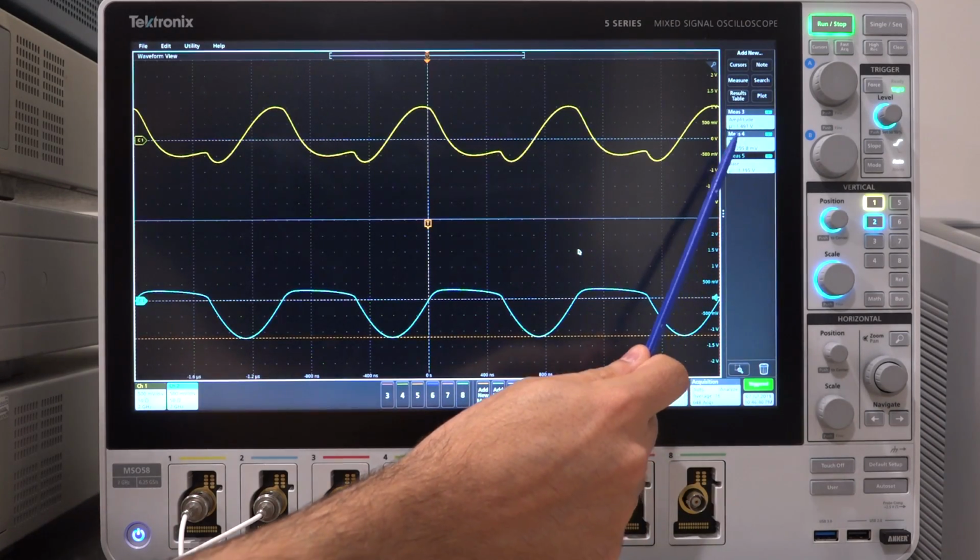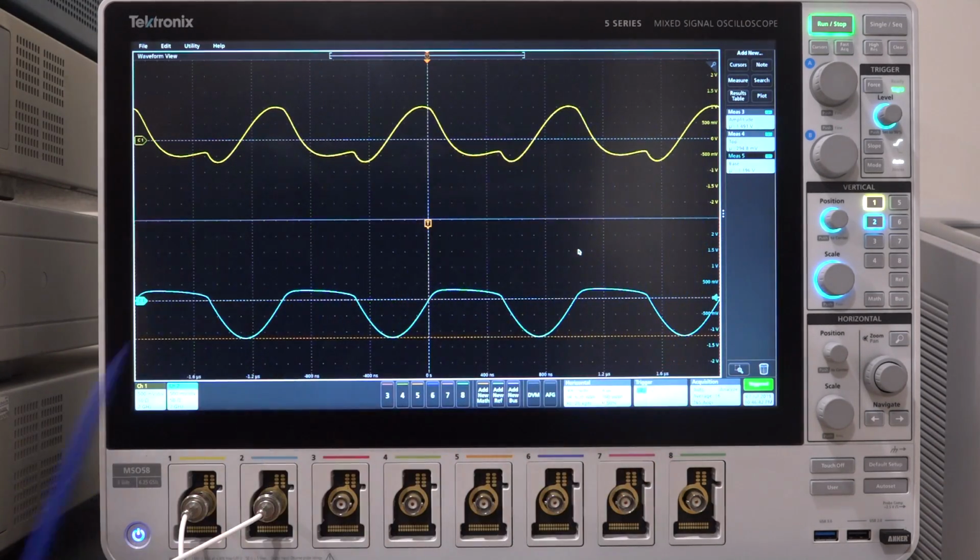And if you look over here, look at that. At the top, you have 290, 200, and about 300 millivolt. Multiply that by 2, you get about 600. And then the amplitude is 1.45. Multiply it by 2, you get about 3. These numbers match what the InstaView told us, and this is exactly what you would expect.